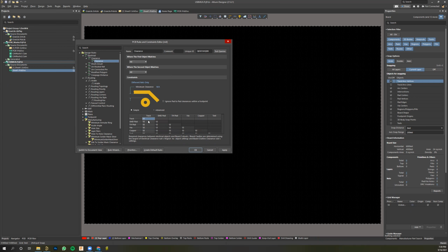And for our purposes, and the manufacturers we use, it is safe to set all of, and I do mean all of these numbers, to 6. By the way, this dimension is in mils. And that's not millimeters, okay? Mils, I don't know where that name comes from, but that is 1/1000th of an inch. Mils are something you will likely deal with a lot in circuit cards. For example, take your standard breadboard spacing. That's 100 mils, or 2.54 millimeters. 100 mils is 0.1 inches, a tenth of an inch. So that's what a mil is. And here we're defining this number as 6 mil. That's kind of the standard unit. So we might mess with clearance.